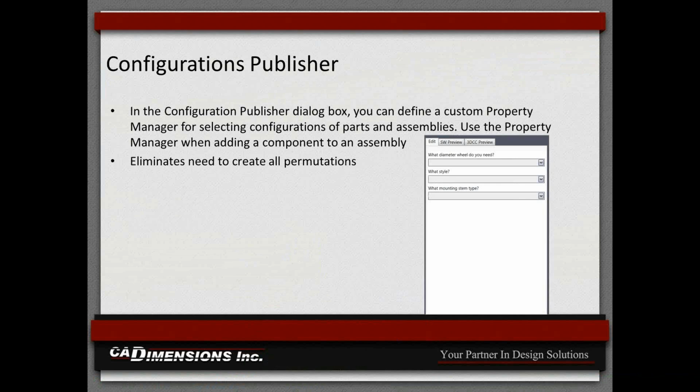Now the last thing I wanted to show before we answer any questions here is something called the configuration publisher. Now I'm not going to go into too many details, I just want to let you know that this exists. Now the configuration publisher takes configurations to the next level. It does require a design table, which I'm going to show here in a minute, but it's a way of creating an interface so that you can create configurations on the fly.